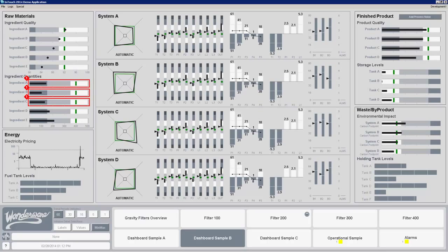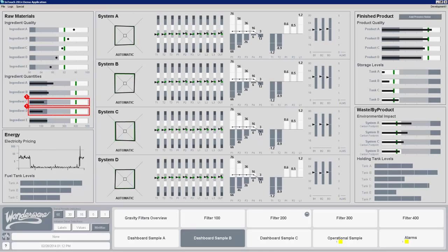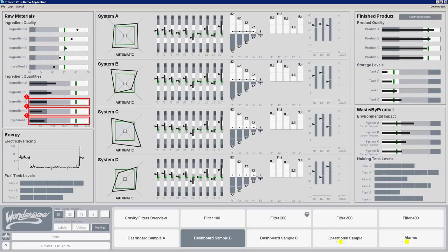The more contemporary ways of building HMIs are talking about a hierarchical organization of your windows into 4 levels. The first level we'll talk a bit about today, which is level 1. The level 1 windows are really intended to provide you a wide overview of the system and provide at a glance awareness of where there is action that needs to be taken.